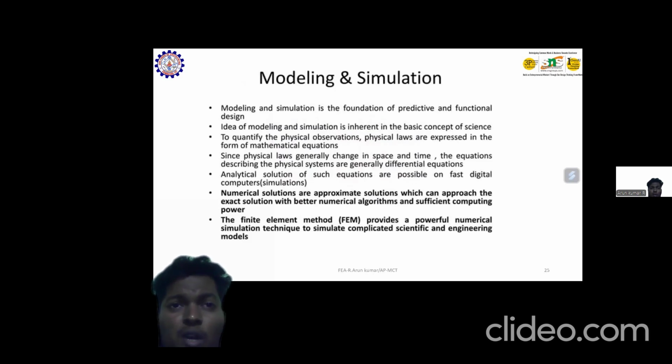After applying the boundary conditions and forming the global stiffness matrix, global force vector and global displacement vector, and eliminating the fixed supports, you get the unknown displacements of the respective nodes. These are the methods to carry out whenever you analyze any type of problem, whether one-dimensional, two-dimensional or three-dimensional, and they are useful for solving numerical problems.